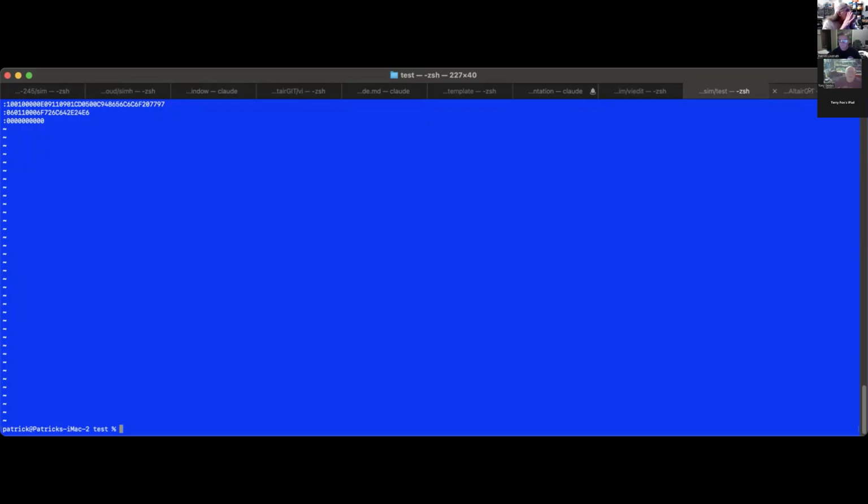I'm just kind of wondering, maybe the TL866 only does 16 characters per line, and I'm sending a 32 character file. This is 32, right? I mean, this is the hex file that I would use. No, it should be 16 bytes, so it's 32 characters. It starts at E09, I think. That should be 70. 32 characters, and then you hit 97. I think mine's even more than that because I'm at column 75.